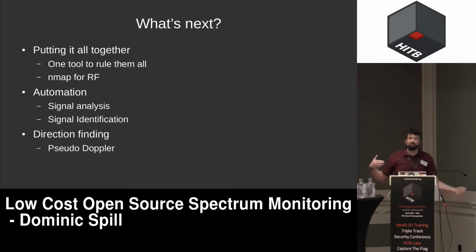What this presentation is about is trying to show which tools exist and where we'd like to take them next. So that's what I'd like to talk about for just another minute or two, which is we would like to be able to have the capture and the visualization and the analysis all in one tool. We'd like to build an open source tool, preferably, that will allow us to receive that 6 gigahertz of bandwidth, and then when we identify a signal that looks interesting or novel or different, we can drill down into it and take a look at what kind of modulation it is using. Let's do a spectrum plot to see if we can tell what kind of modulation it's using. Let's try and decode it in some way.